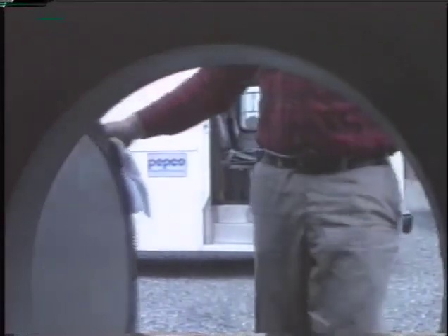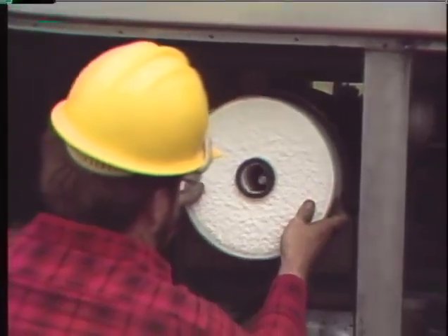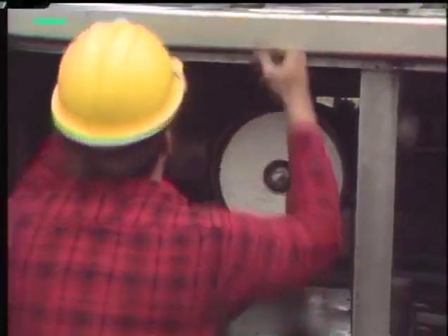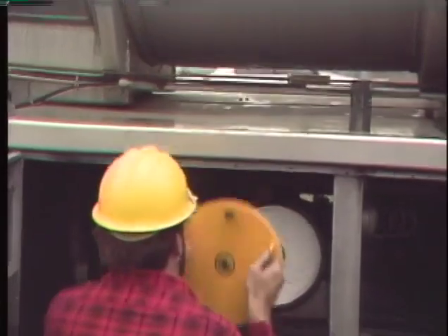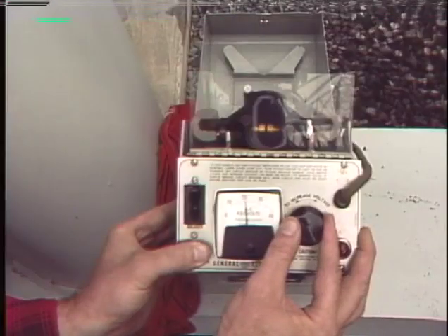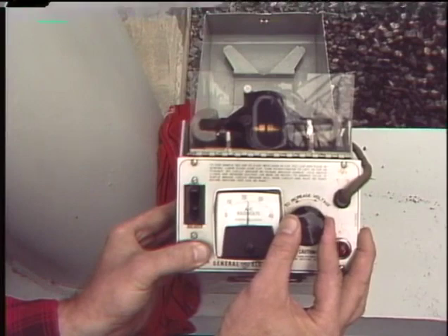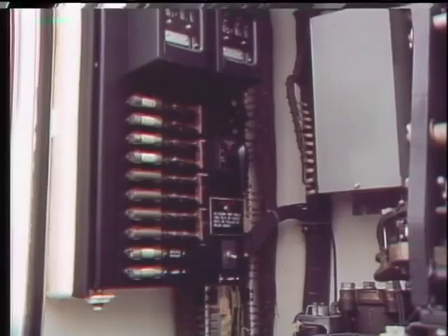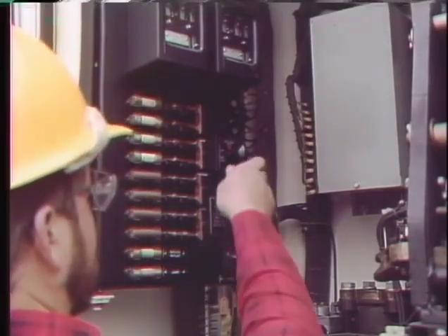When all the checks are completed, the arcing grids and any other parts that had been removed are reinstalled. The breaker is closed and refilled with oil. New filters are put in the filter press, and the oil is filtered a second time when it is pumped back into the breaker tank. After the oil is back in the breaker, a sample is taken and its dielectric strength is rechecked. Finally, the breaker is operated electrically to ensure that it works properly.